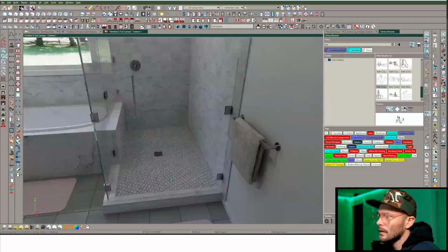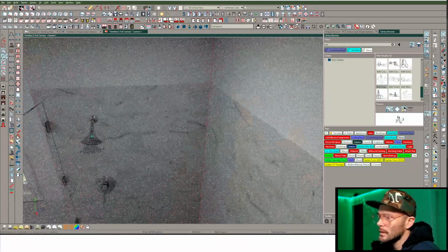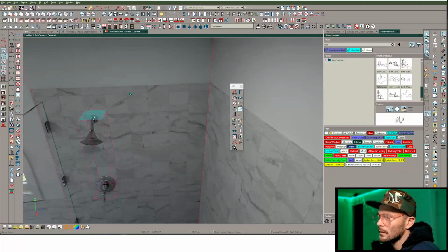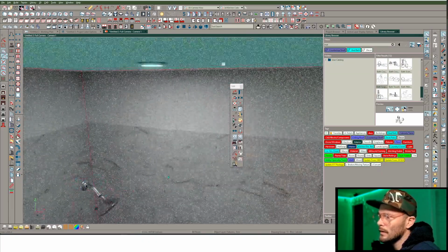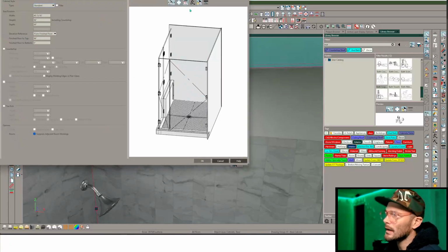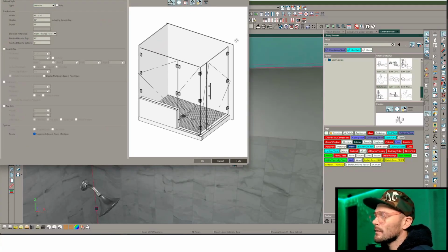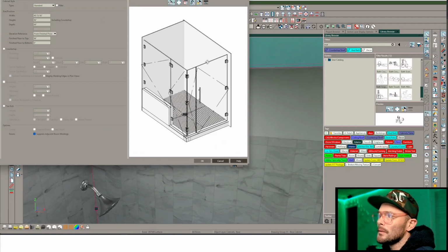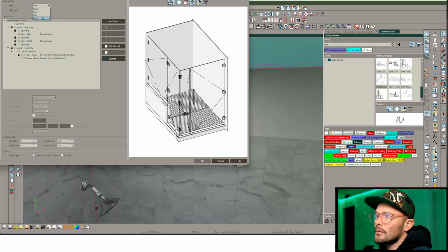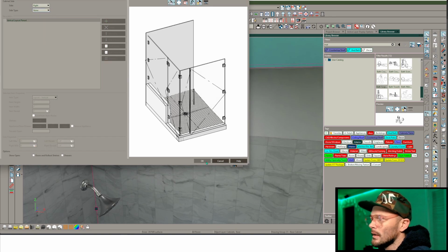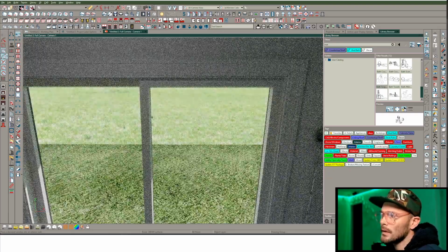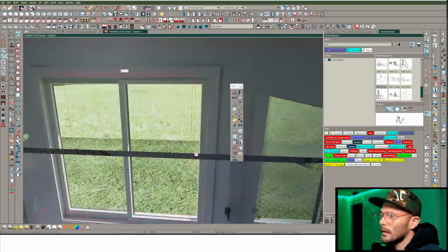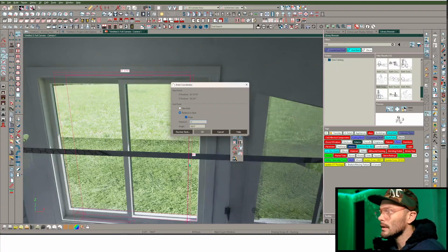I can find center. Oh, this is still an architectural block? No, it's not. Should have been able to get center, but I'm gonna be fighting it. Okay, so this is a cabinet, believe it or not, and it's infinitely resizable and modifiable, which is very, very cool. And so what I need here is the right side is this plane here, and we're just going to say none. So we're going to take that away because I'm going to put a window there instead, which means we get to throw this window in here, and let's shrink this down by 12 inches on either side.